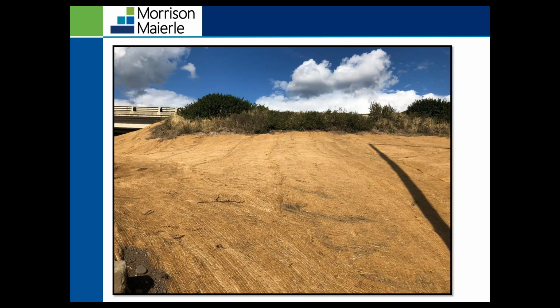Right here we have erosion control blankets. It is an erosion control BMP designed to temporarily stabilize soils, protect disturbed soils from erosion, reduce rainfall impact, improve infiltration, and promote vegetative growth. So if we're using this BMP, there are some alternatives to it. There's hydraulic or straw mulch or temporary seeding.